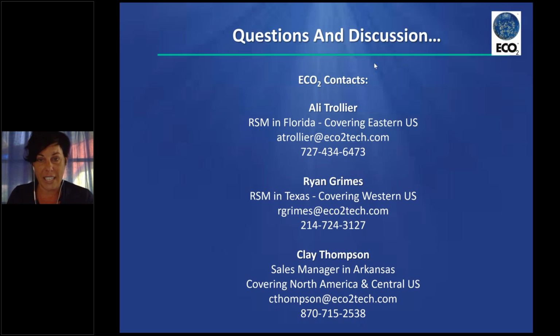Also, the last question I see here is, are full-scale case studies available to demonstrate proof of this concept? And Dick, I think I might field this one if you don't mind. We do have the full-scale case study for the primary clarifier superoxygenation that was in Madison, Maine. However, we do not yet have a full-scale case study for superoxygenation of a secondary clarifier, but we are really open to looking for that pilot case study and a partner to work with where we can do some of this testing.